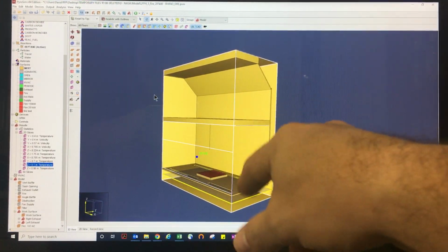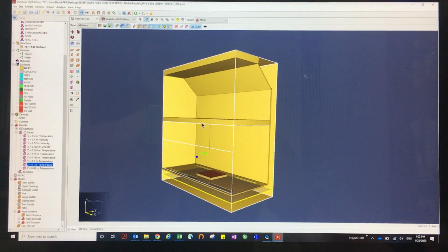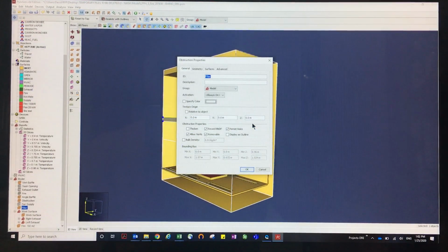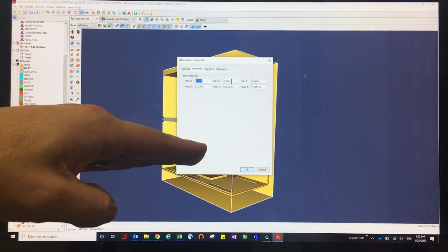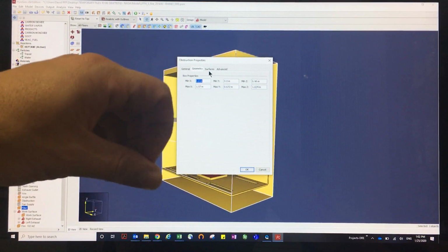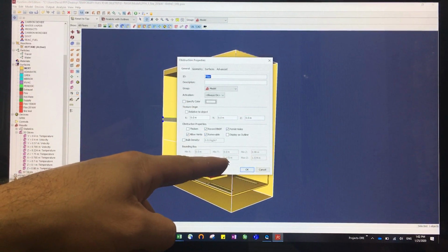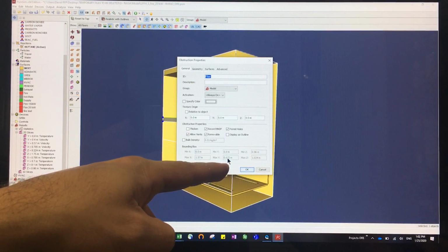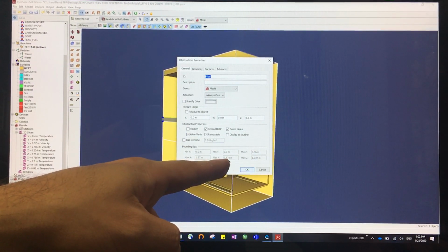One thing that helps to figure out the height of the sprinkler is you can select this one, for example, double click on it just to see what coordinates it has. Geometry. So the height is, box properties, yeah, I guess it's 0.667. So you want to put the sprinkler just 10 centimeters below that, then it will be 0.57.